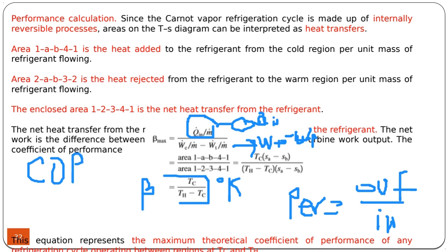So we can call it the reversible COP, and the reversible COP can be calculated using the temperatures only. Otherwise, we have to use the definitions of Q and work. As a general definition, the COP is always Q divided by W, but for a reversible Carnot cycle, we can use the temperatures instead of Qs or works.